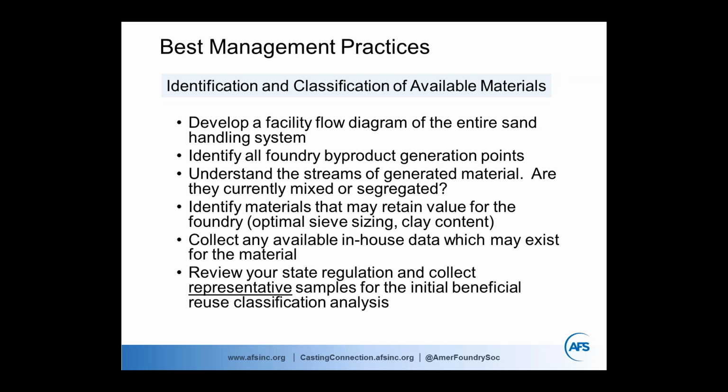Another thing that's important is to understand the definition of foundry sand in your state. Some we think of as straight-up sand, but actually in some states that can include baghouse dusts that were collected off sand conveying systems, or it could even be cores or core butts. So make sure you understand that definition within your state, and as you develop the flow chart for your facility, you can keep in context those things that are going to be available and applicable for use in that state. And one thing that I think is often missed straight up is, no matter how wildly successful you are with reuse,